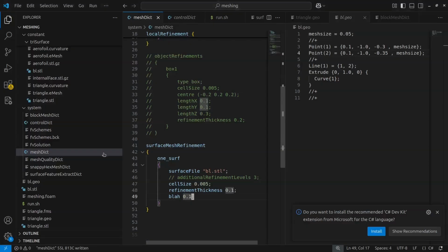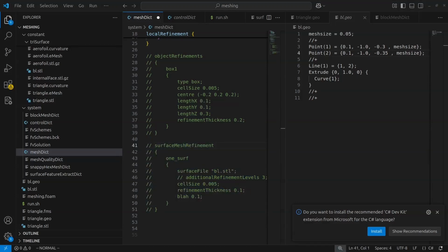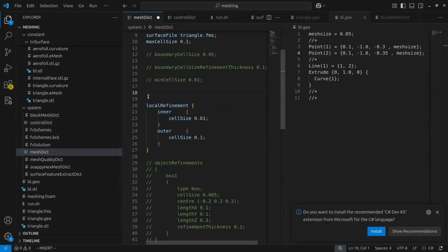This is very useful. Now next thing is keep and remove cells. You should have very thin gaps and then only we can simulate this. CFMesh gives you the option to keep some of the cells which are intersecting a very thin surface.